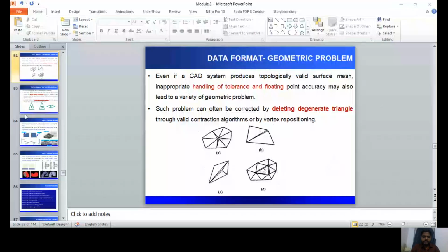So these are the different ways in which you can generate triangles, and you can overcome the issues associated with triangles. And I hope in this lecture you all were able to understand the need for the STL file and how the STL file looks, how to save the STL file in CAD software, why we require the STL file for additive manufacturing, and what the problems associated with the STL file are and how to repair them.